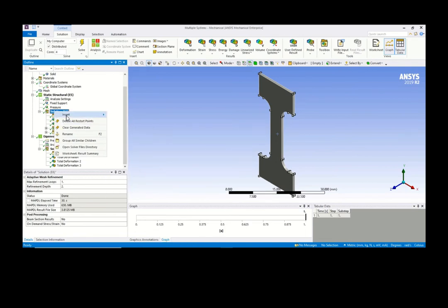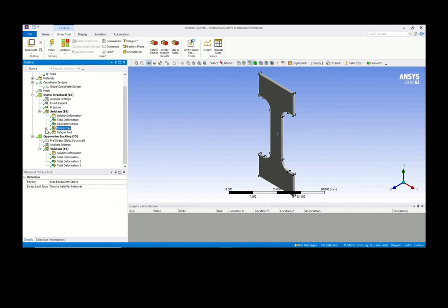If you click on this, insert stress, maximum equivalent stress, it will pop out. If you expand it, you will see there is safety factor coming in here. This safety factor basically gives you the N. If N is larger than 1, then it's considered safe; lesser than 1 is considered not safe. But if you want a higher safety factor, say 2, then larger than 2 is good, lesser than 2 is no good.